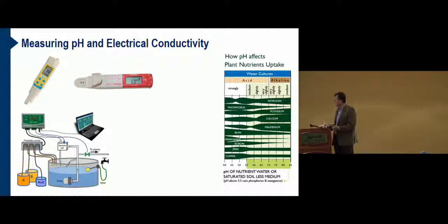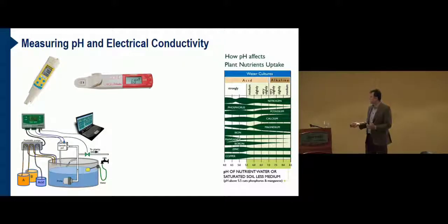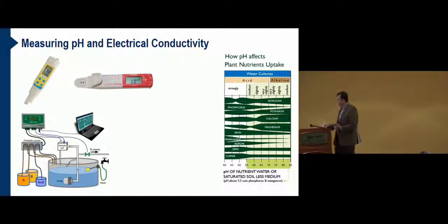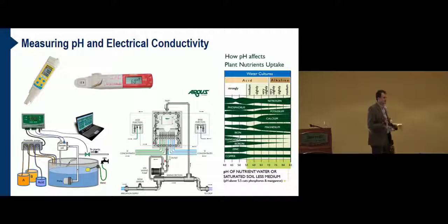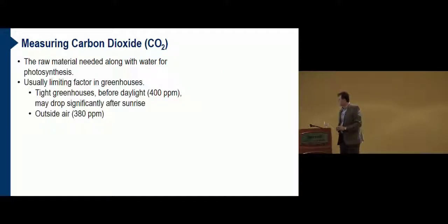Those, for example, use concentrated solutions of nutrients and maybe a diluted acid solution, using peristaltic pumps to inject these solutions and mix them with water based on sensor feedback, as you can see here. Or you can find more sophisticated systems where you have more integrated, more distributed monitoring and control capabilities when it comes to nutritional management.